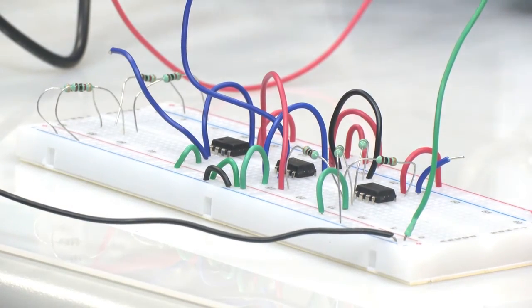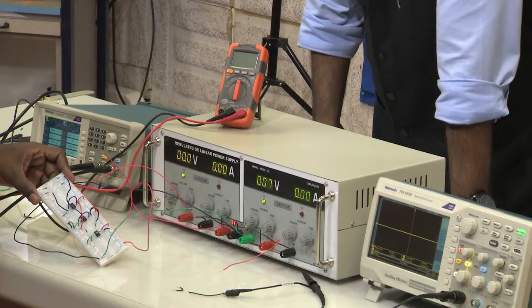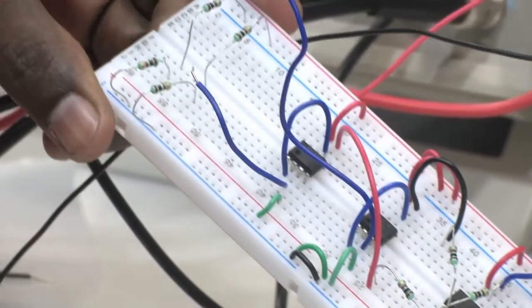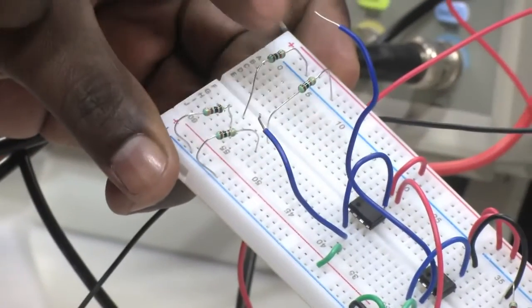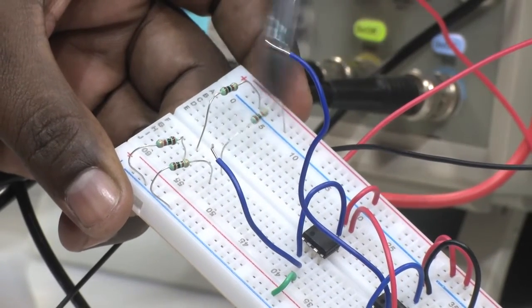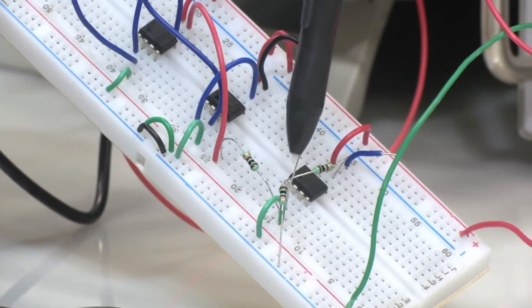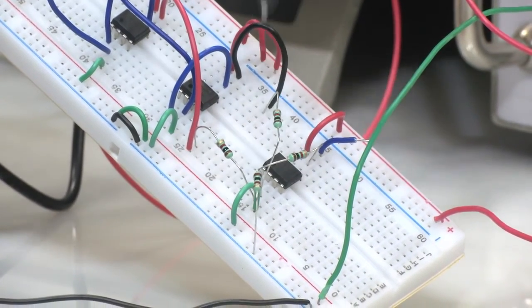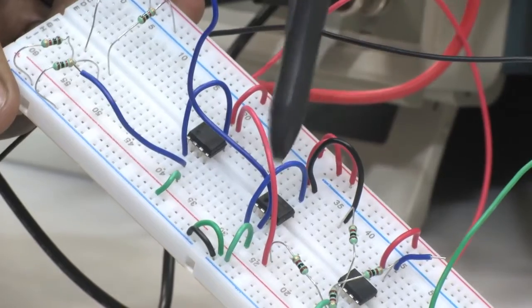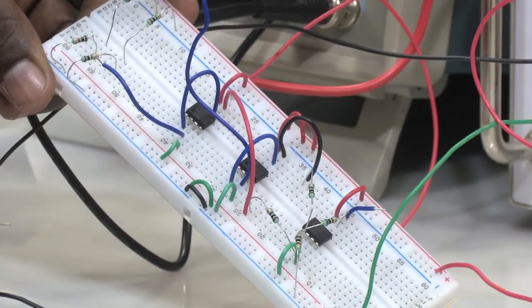So, what he has shown is a Wheatstone bridge, which is 4 resistors. If you can focus here on these resistors, please. You can see here 4 resistors. So, this is a Wheatstone bridge, and then the instrumentation amplifier is somewhere. Can you please show the differential amplifier? This is the differential amplifier, and to this differential amplifier we are connecting buffers. Where are the buffers? This is 1 and this is 2. There are 2 buffers, 1, 2, the differential amplifier is here and the Wheatstone bridge is here.